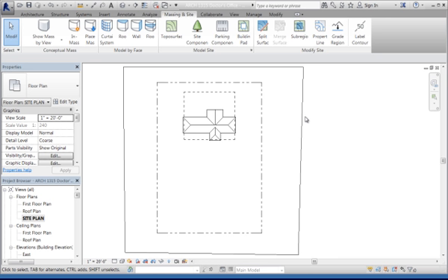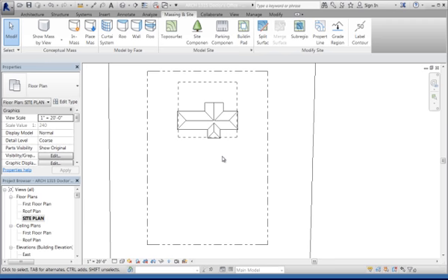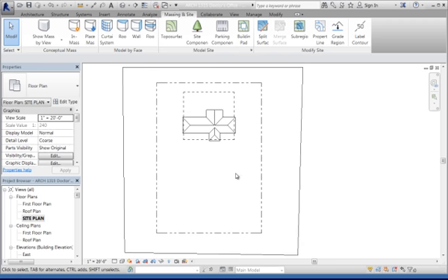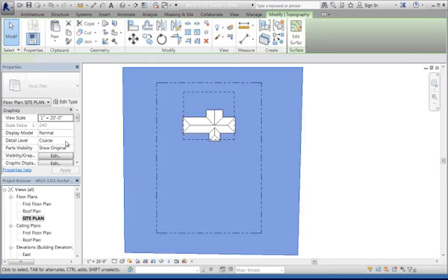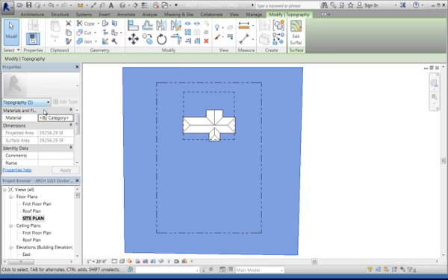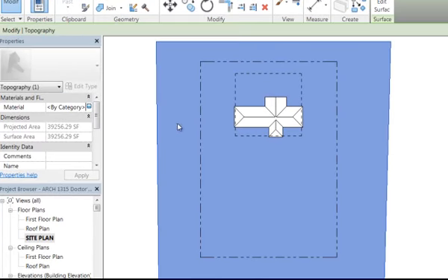So within this surface, you're going to start thinking about where you want your hardscapes. I'm looking at the site plan assignment. Hardscapes meaning anything with concrete. Sidewalks, curbs, gutters, and roadways. And I suggest you kind of sketch this out first before you try to just figure it out on here. But right now, this whole site, if you highlight it right there, topography, and over here in the material, you can just change it, make sure it's earth or grass, whatever you want it to be.